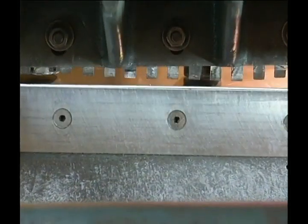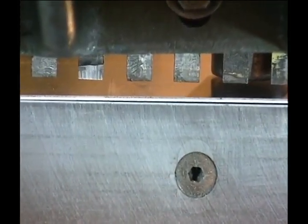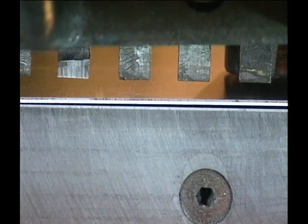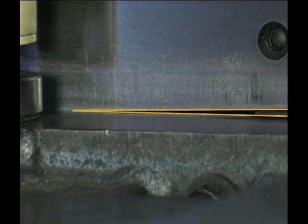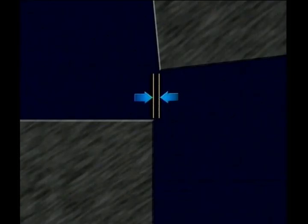In most shearing operations, the edges of two knives, a fixed lower blade and a vertically moving upper blade, meet progressively from one side of the workpiece to the other to shear the material like ordinary hand shears. The angle at which the upper and lower blades are aligned with each other is called the blade rake or shear angle. The distance between the upper and lower blades is known as the blade or knife clearance. Knife clearance is essential for proper shearing and is modified for different material thicknesses and strengths.